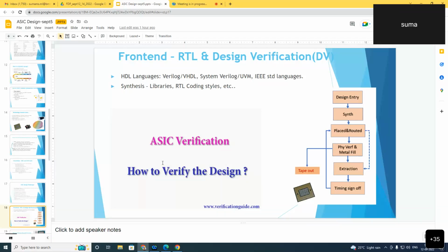And these can operate at more than one operating condition, typically minimum, maximum, and typical. There is a set of operating conditions defined in the library to specify the process, temperature, voltage, and the RC models. So these are used during synthesis and timing analysis of any design.